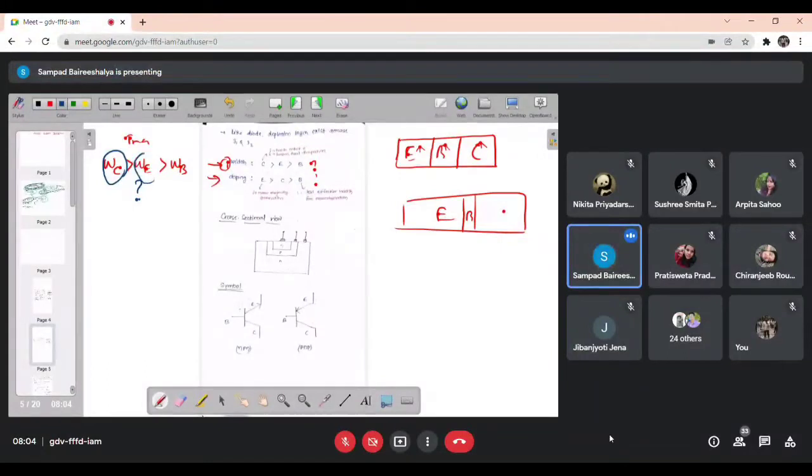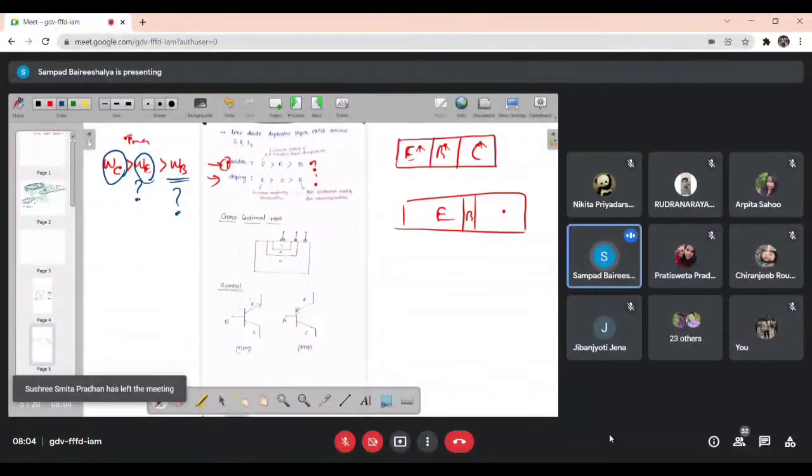Okay, then why is the base area less? The base area is less because in the base there will be recombination. If bank charges are more, there will be more deduction in the money, and less money will be credited to your account. In the same manner, if your base area is more, there will be recombination. What do we mean by recombination? The electron-hole pair gets recombined. As the electron-hole pair gets recombined, the number of free electrons will reduce. Is that clear? If the number of free electrons is reduced, fewer carriers will move to the collector.